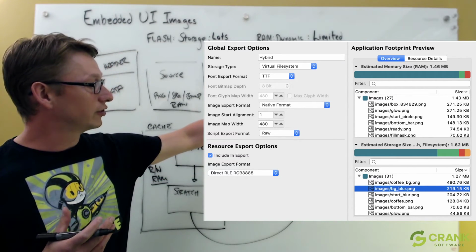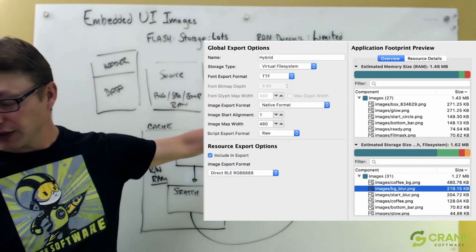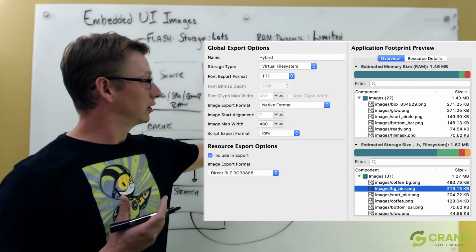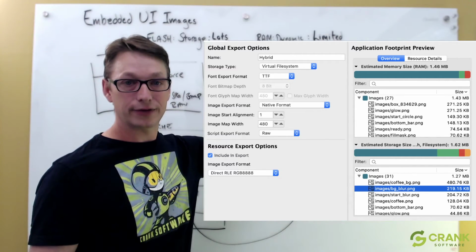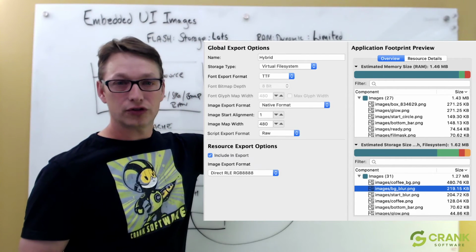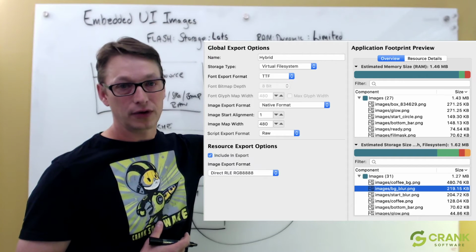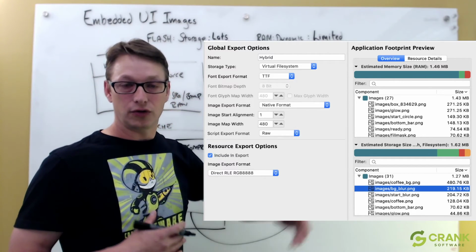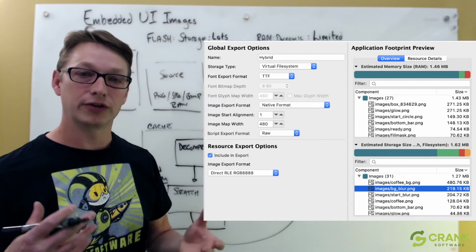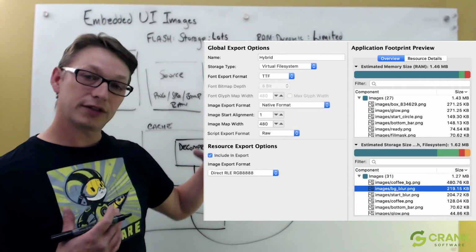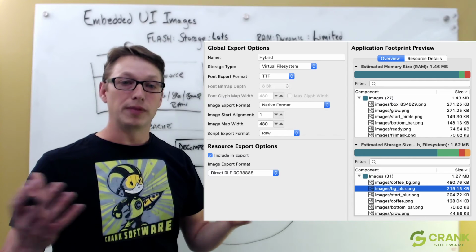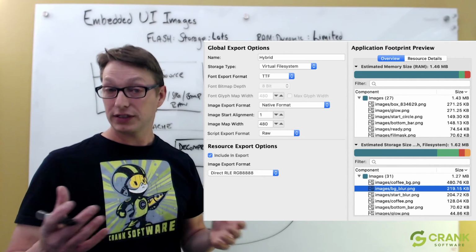So if I'm looking at 480 by 272 on our display, and I'm at 24-bit color, so I've got full 888 for my RGB, red, green, and blue, I'm looking at something just under 500K for this. If I go to 16-bit, so a 565 color format, 5 bits, 6 bits, and 5 bits for my red, green, and blues, I decimate the number of colors. I chop the frame buffer memory requirements in half, so that's a big savings.